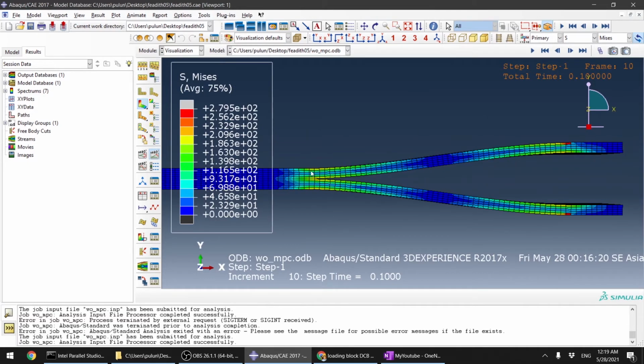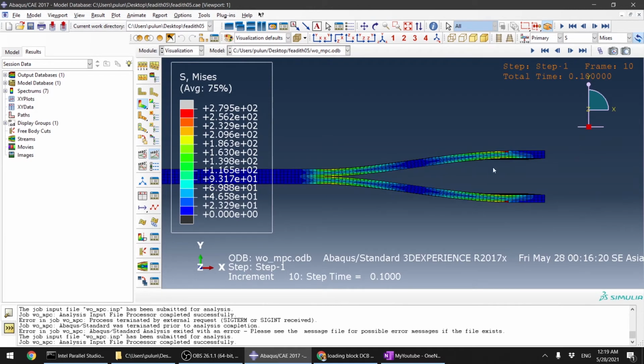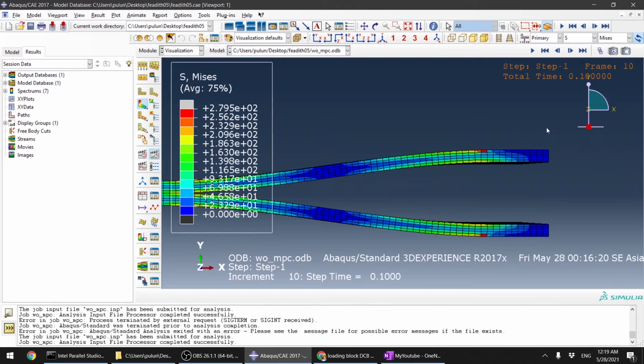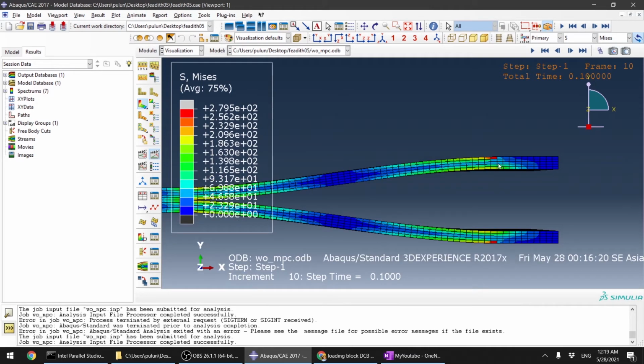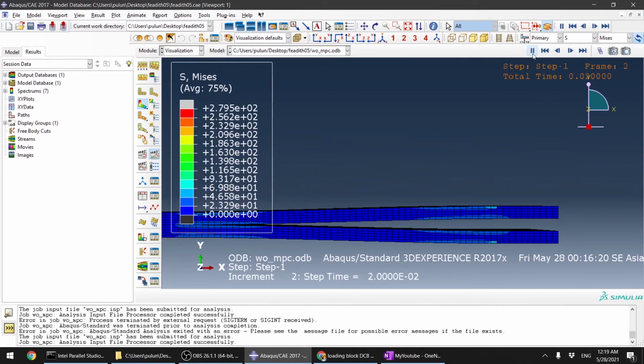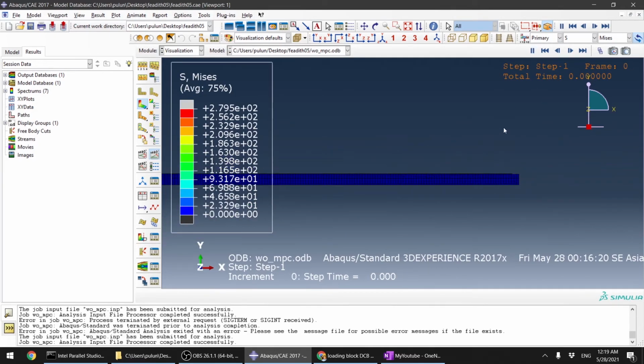So as you see here, there is an opening here, but the way the beam deflected is a bit strange. In the experiment, it should be nicely curved like this, right? Straight like this, while this guy is now like this. Why? Because you give uniform displacement to this 10 millimeter beam area, right? So all of this beam here, they have the same displacement. In this case, it's still 10 because total is 100 millimeter displacement above. Now it's only 10%, so it means now they are deforming 10 from here. So this is what I mean. Yeah. So this is strange and this is wrong, right?